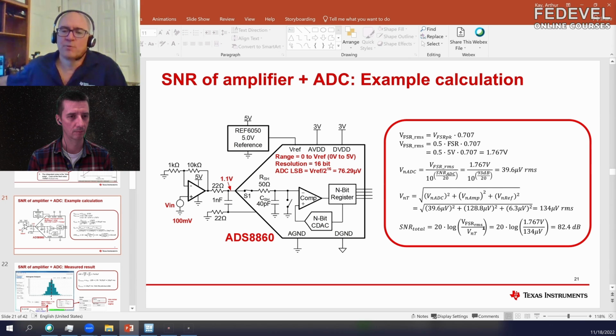So when you're trying to make a low noise system, you really have to identify what's the problem, because of the way noise adds as the square root sum of the squares, the dominant source really will take over. Oftentimes when you add numbers together in engineering, there's kind of a rule of 10. So if something's 10 times greater than something else, you ignore the smaller element. But because we're squaring things with noise addition, there's kind of a rule of 3. If one noise source is 3 times greater than the other noise source, the larger noise source is going to dominate. So in this case, it's substantially more than 3, or at least more than 3.